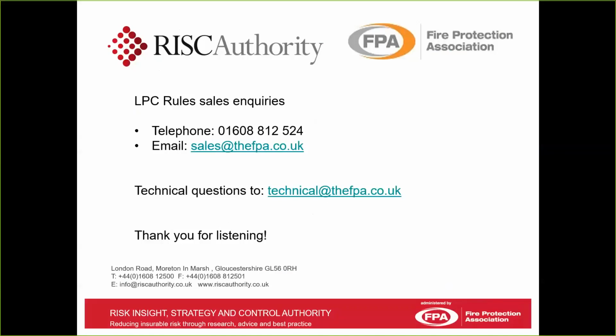There was a question mark here about whether the Annex D 20mm flushing valve is now necessary or is now going to be affected by this new clause on flushing. Some people are using this 20mm flushing valve to test the flow switch alarm.